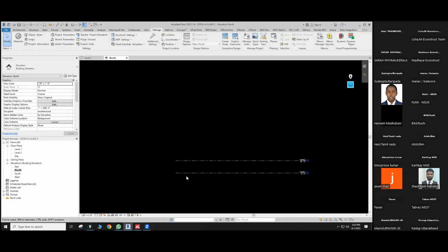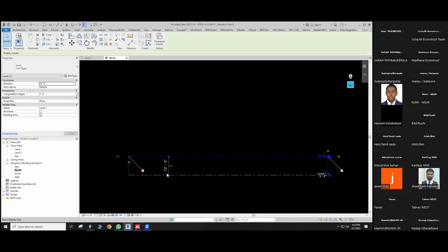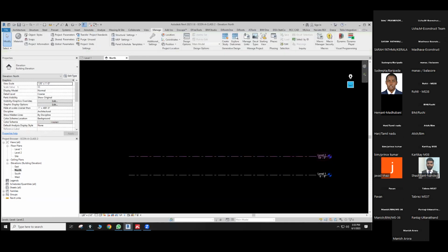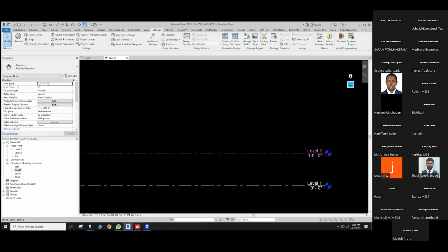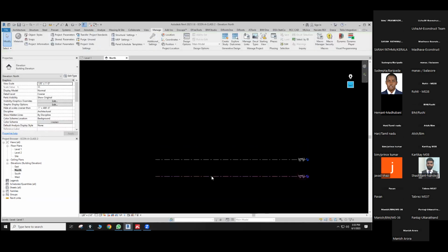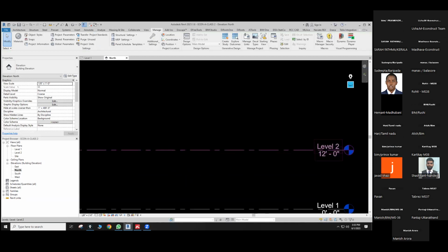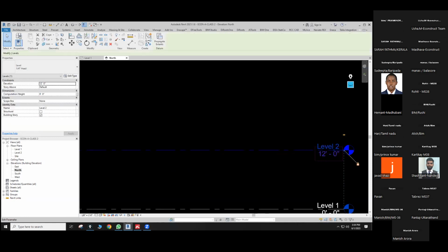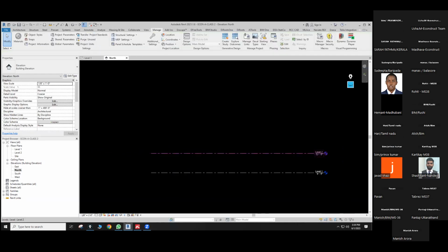So this is the level, and for example, what is another constraint? This is the dimension constraint. See, this is the dimension constraint. For example, this is 10 feet. So we just double click over there and keep it at 12 feet. It's over. This is one thing. Another one, we can directly go for the dimension constraint. This is the thing with which we change the height of the level. This is the level text, but I'm not changing the height of the level text at this time.